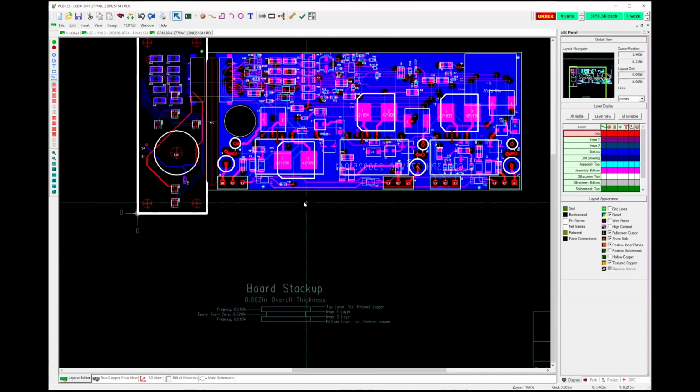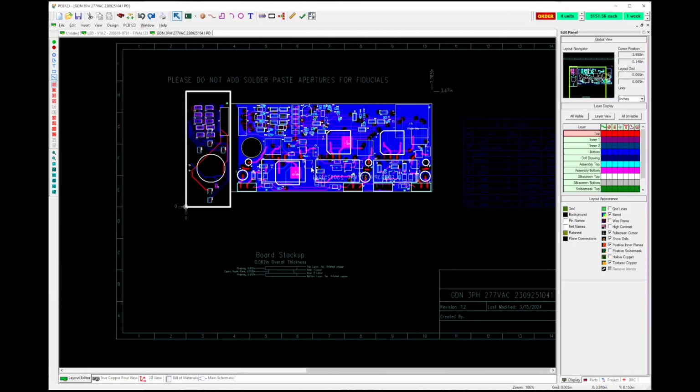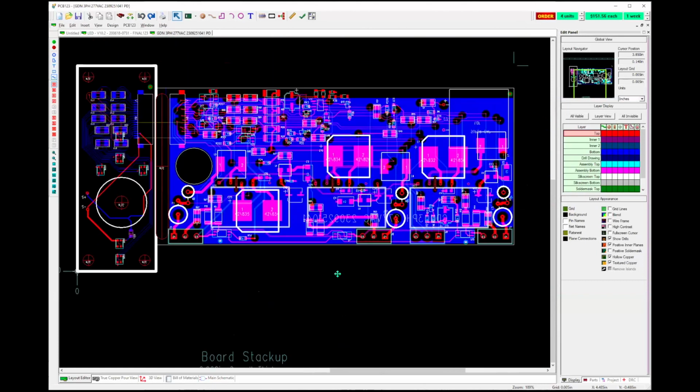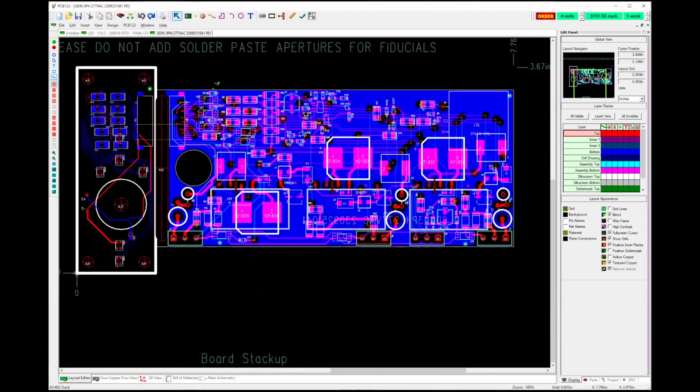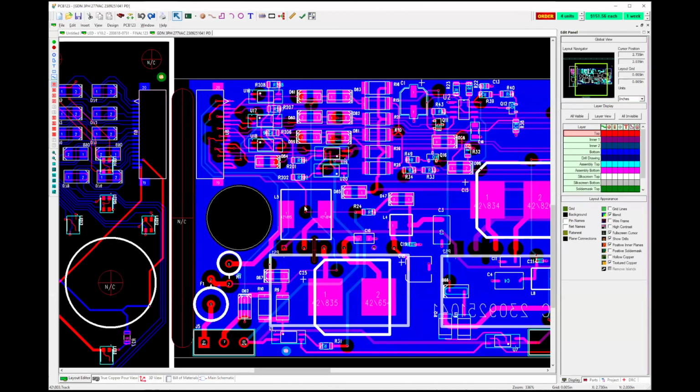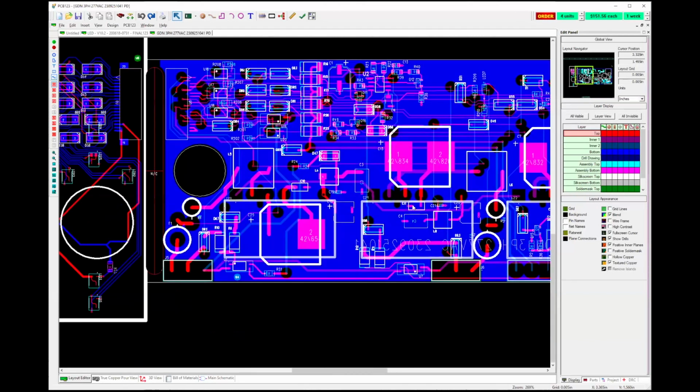Another feature that the tool has that's very nice is the ability to put in power planes and then route around them, so long as they're hooked up to the correct net and you get clearances that are appropriate. This is a pretty high voltage board, so I give it pretty large clearances around some of the wires to allow it to not arc or to be interference.